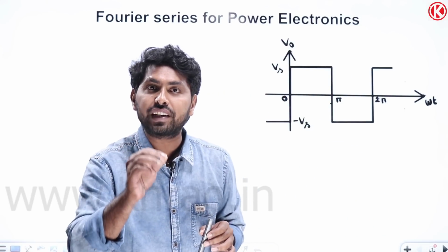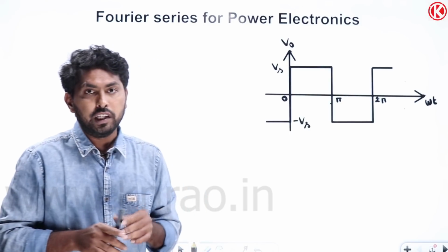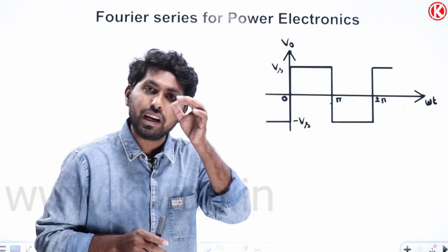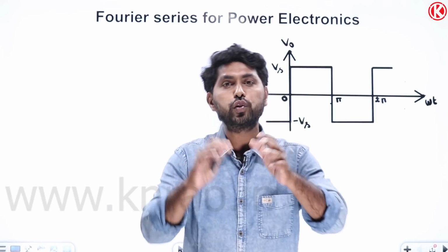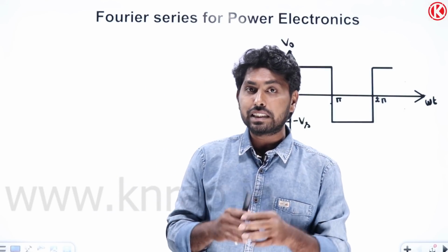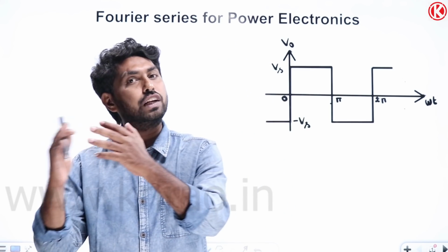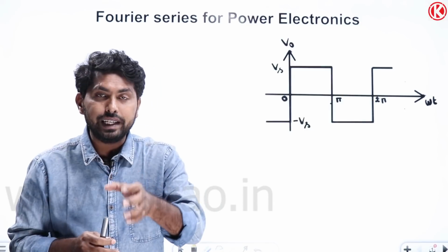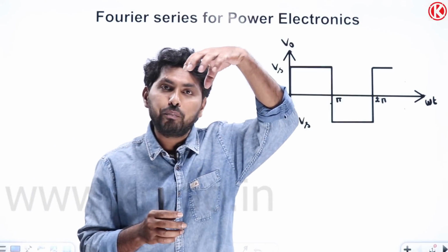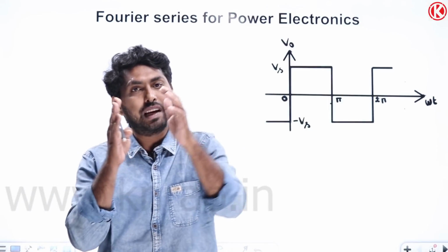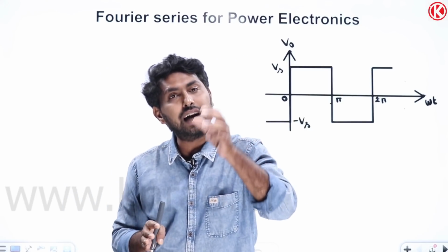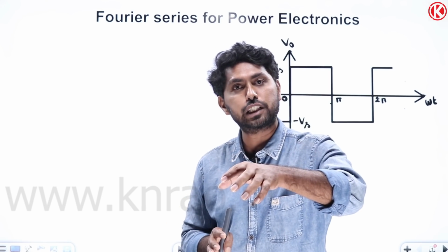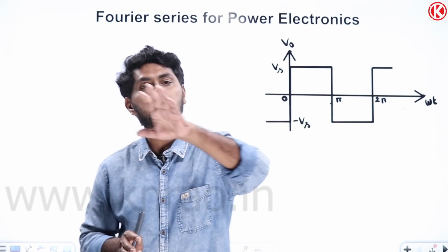If you spend 30 minutes on this video, you can write the Fourier series expression of any waveform which you will come across in power electronics, that is, the current and voltage waveforms of the rectifiers as well as the inverters. And one more thing: by memorizing the three waveforms, or by doing the Fourier series for the three waveforms, you can write the Fourier series expression for any waveform in power electronics.